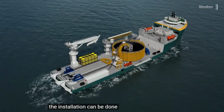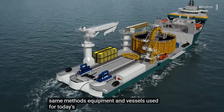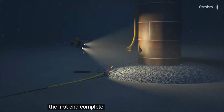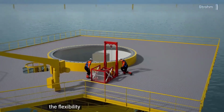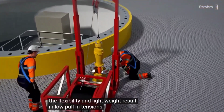The installation can be done with the same methods, equipment, and vessels used for today's wind farm electrical array cable installation. The first end, complete with end fitting, is pulled in through a J-tube. The flexibility and lightweight result in low pull-in tensions.